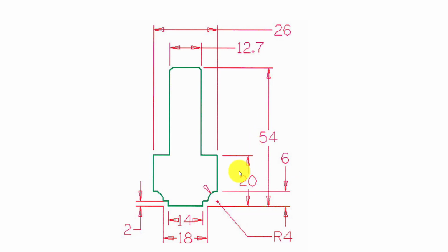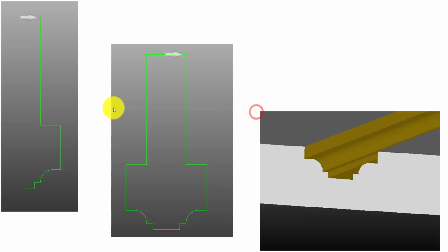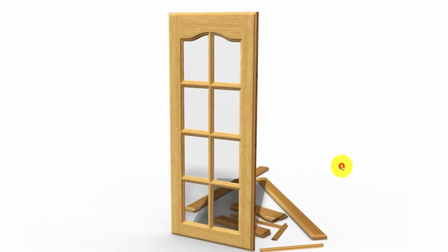So when creating a new tool for use in Alphacam, you can see we've already dealt with actually drawing the profile, the shape. So typically you're given the shape of the tool. And so as we've seen already, we draw half the profile, mirror it over to get the fully enclosed watertight shape, and then create a tool. And as you can see on the right of the screen here, then whatever that profile is, that's digitally what Alphacam will have as the cross-section of the cutter.